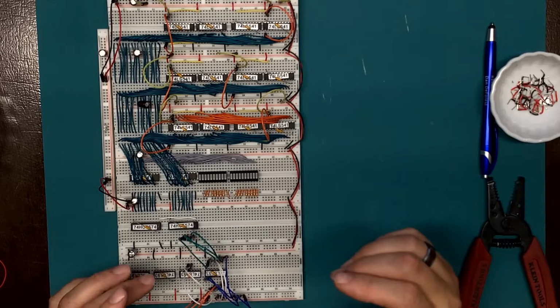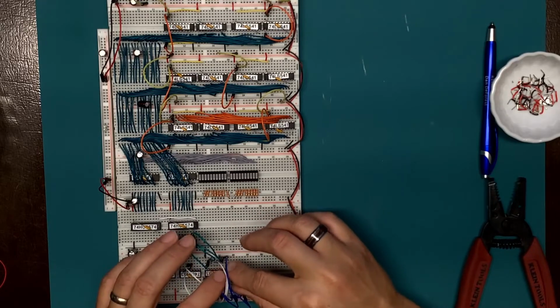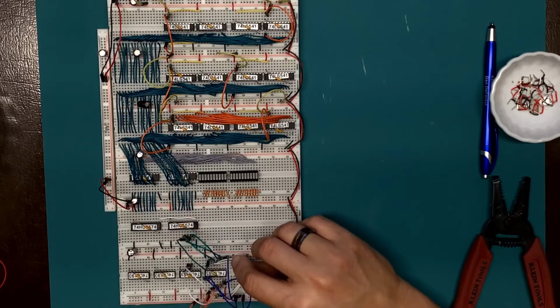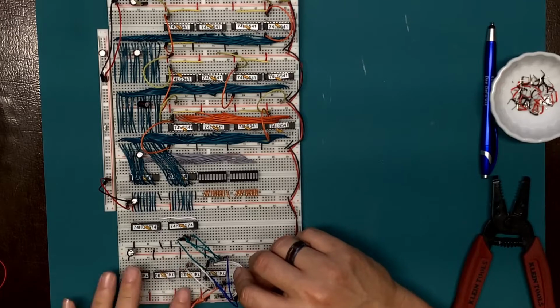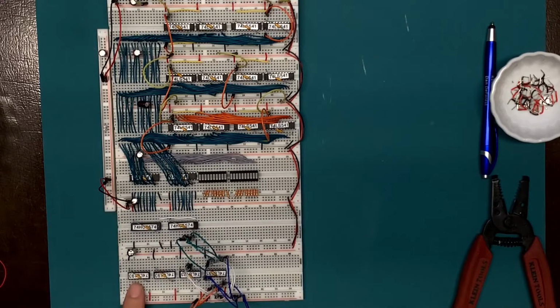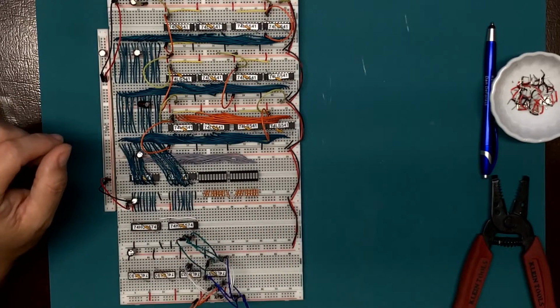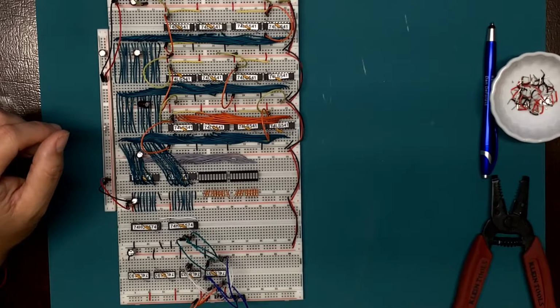So, everything but these 2 white wires here on the first integrated circuit get replicated up, except these 2 white wires have nothing else to go to on the end. So it basically ripples its way up from the least significant bit to the most significant bit. Let me get that all wired up then.